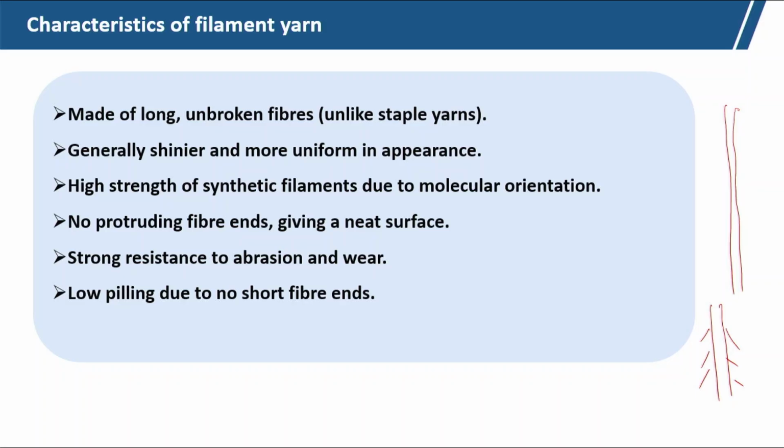Peeling is effectively not there. They are free from short fibers, and for low microdenier filament, after breakage they may form peels to some extent, but peeling in the case of multifilament yarn is not commonly visible. It feels smooth, but is less breathable than staple, that is okay.